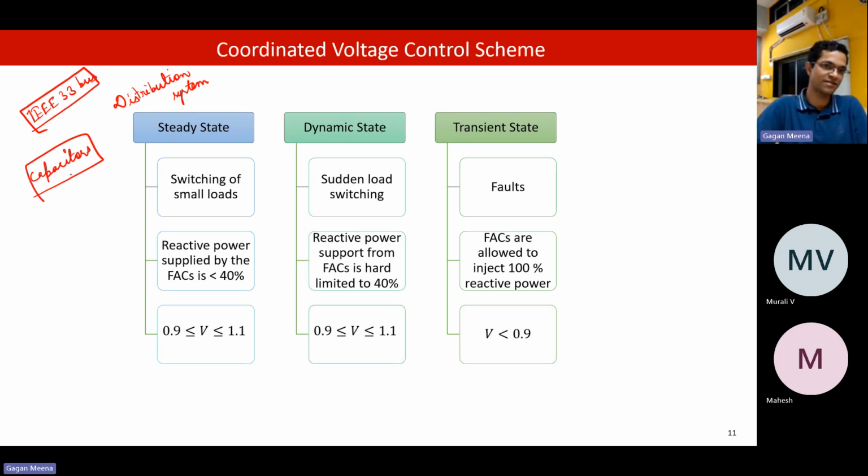We can use capacitors, but generally we have these in distribution systems. These are radial systems, right? And capacitors are generally used to do local control. Power electronic devices are also there. They are generally used by the consumer itself and provide better local control. But if you want to improve the voltage profile of the entire feeder, then other devices are used.